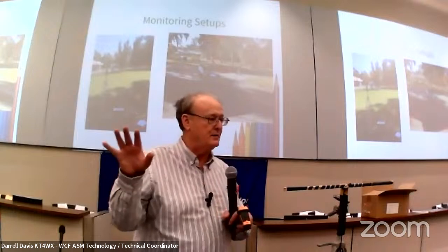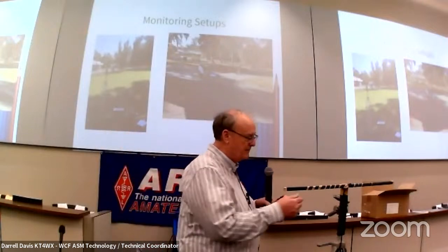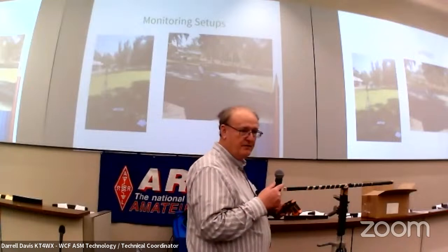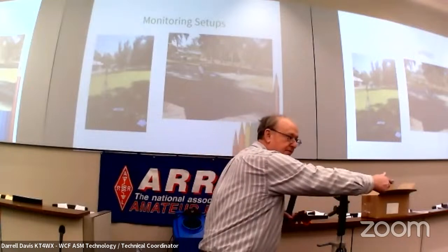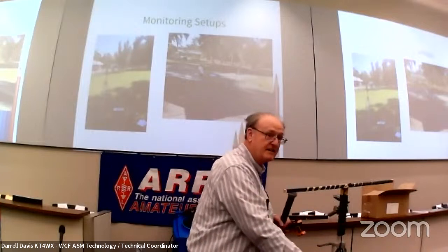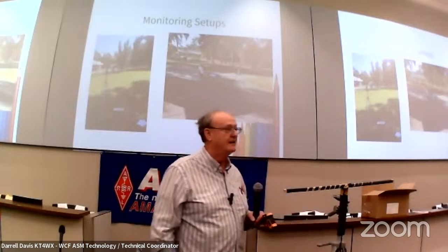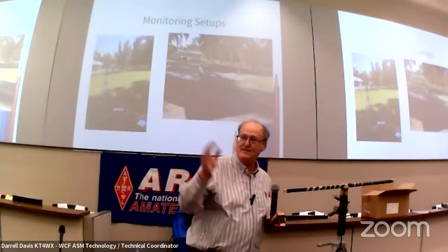And anybody can do this. This is not hard. If you duplicate this antenna, which is real simple, it's 1 foot of shield this way and 1 foot of center conductor that way, and then 10 feet of RG8X, connect to your spectrum analyzer, done. $3,000. Did I have any takers?